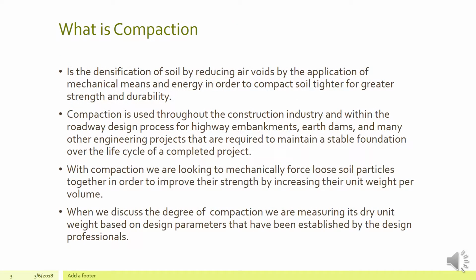So what is compaction? Compaction is the densification of a soil by reducing the air voids within the soil by the application of mechanical means to compact the soil tighter and tighter together, because we want to get greater strength and durability out of it. Once we disturb a soil and start doing excavation work, we've loosened it up. We've all dug holes and put the dirt off to the side, and then when we go to fill the hole back up, we've got more dirt than we started with. That's because it's broken apart and expanded. So we want to get those particles to go back together again, moving in and filling these voids, and we use mechanical means to do that.